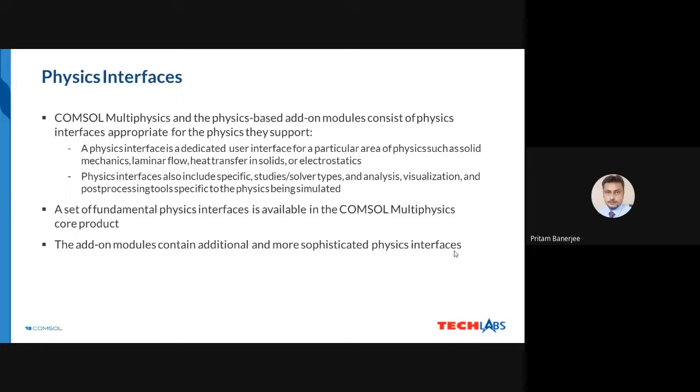Apart from that, inside it, what exactly will be the study, or what will be the solver: the time domain solver, the frequency domain solver. What type of analysis he is trying to do, whether it is a parameter sweep analysis, transient analysis, or frequency domain analysis. He could be using that type of analysis as well. So inside that physics we use those types of solvers.